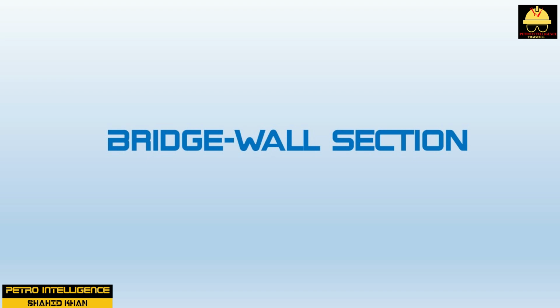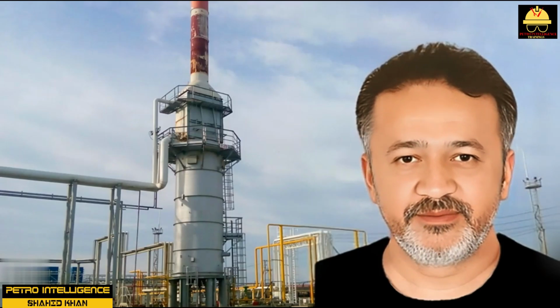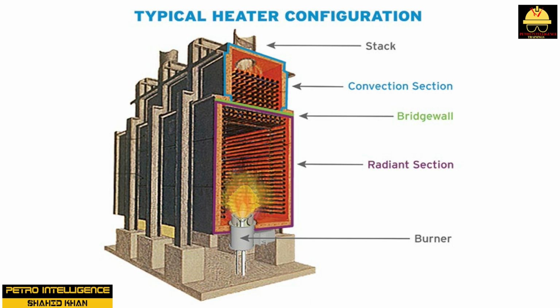Bridge wall section. The bridge wall section is the sloping section of the upper furnace that connects the radiant section to the convection section. It is designed to accelerate the flow of hot combustion gases out of the firebox and into the convection section and stack. The bridge wall is the wall that separates the various sections in the firebox. The heat-reflective materials in this area are designed to withstand temperatures between 1,600 degrees Fahrenheit or 871.1 degrees Celsius and 3,300 degrees Fahrenheit or 1815.55 degrees Celsius.